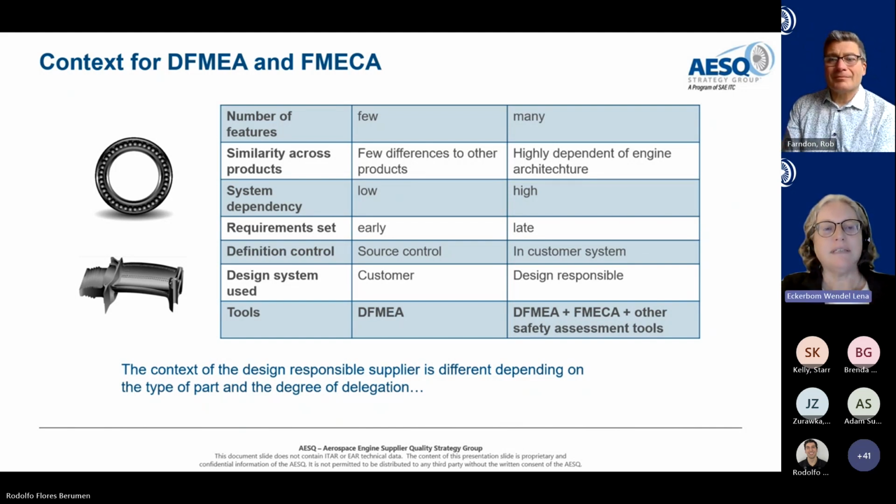If it is complex, highly dependent on the engine architecture, and you get the requirements very late in the development of a new engine, then you need more of an FMECA to support the design accountable party with the information they need to do the system safety assessment on their level.